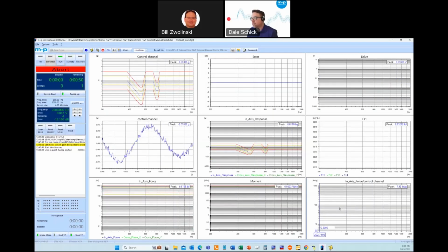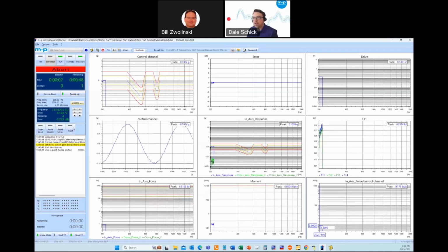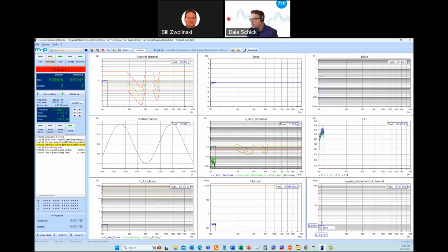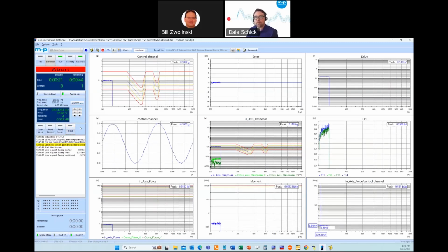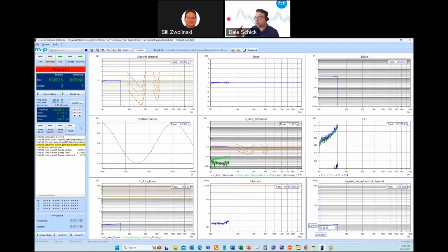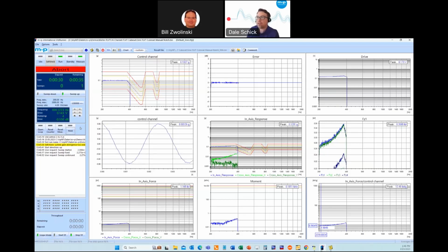So if I start running here, we're building up to 200 Hertz. I can hold the system here and then look at my cursor, and I can see I have about 8.9 pounds force in-axis, which is about the amount of mass that the CubeSat, the expander head, the force ring, and all of the fixturing, all of the instrumentation, and even the little bit of bolt that protrudes above that expander head, or above that force sensor, which is preloaded, those all have to factor in.